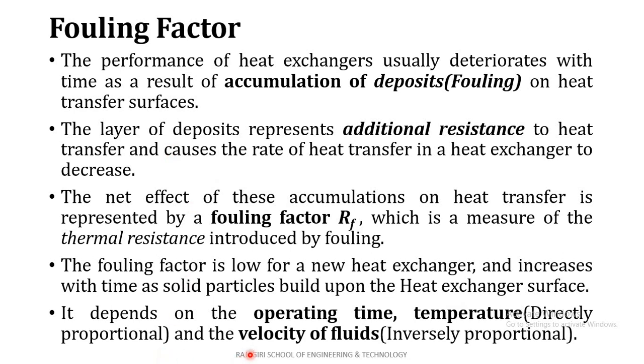But if the fluids move faster through the heat exchanger, then the fouling factor will decrease. There is not much fouling if the fluid moves faster, or if the velocity of the fluid is higher, then the fouling factor will be lesser.